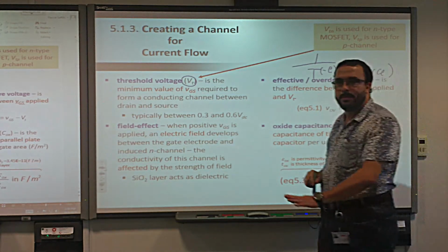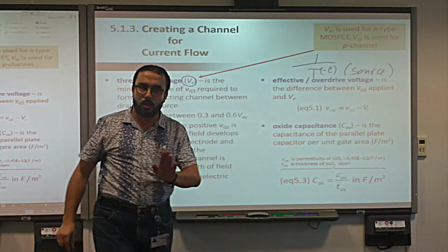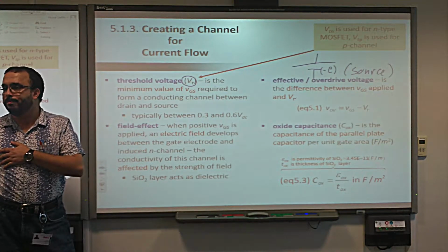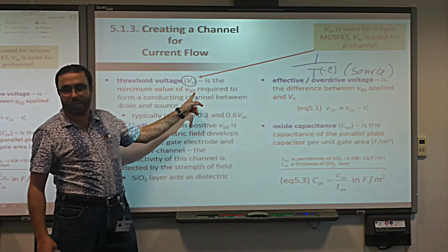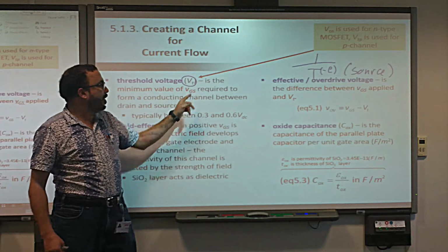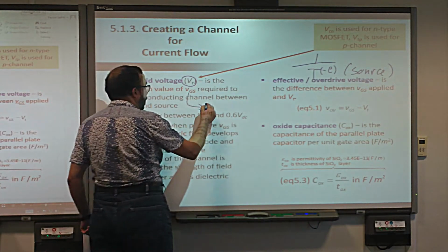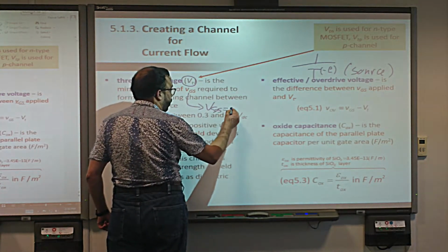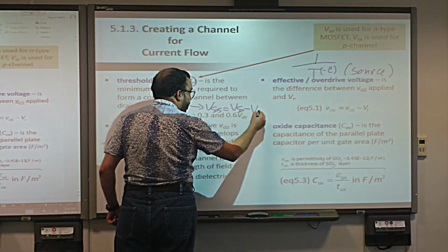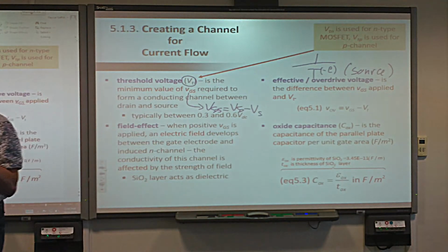You understand? Same thing for the MOSFET. The source is the lowest voltage. That's why we refer to it as VGS, not VG alone. And VGS means what? Remember this? We'll repeat that again. VGS is actually VG minus VS. So it's the voltage with respect to the source. Okay?